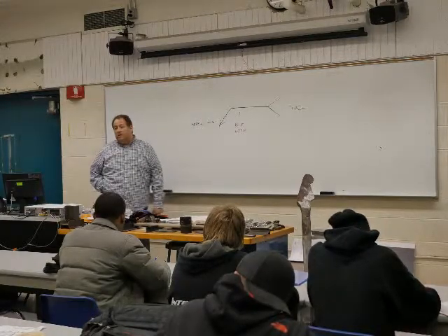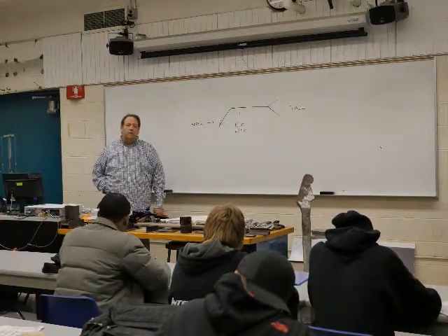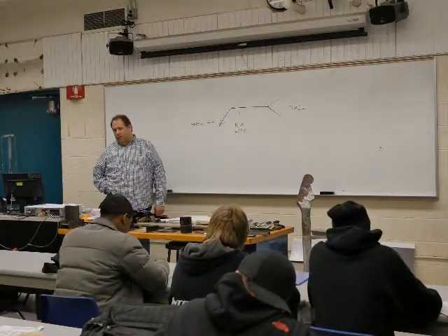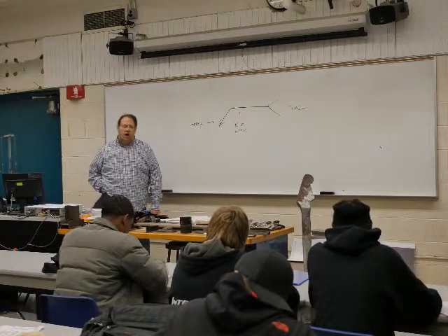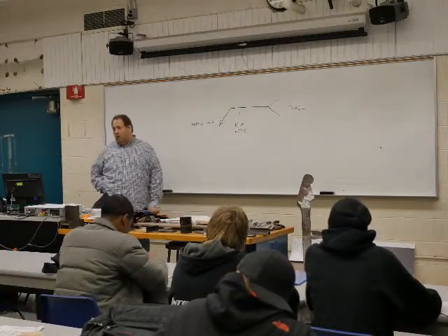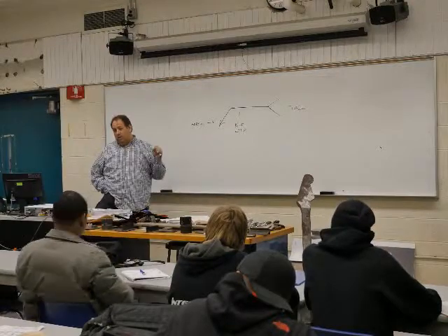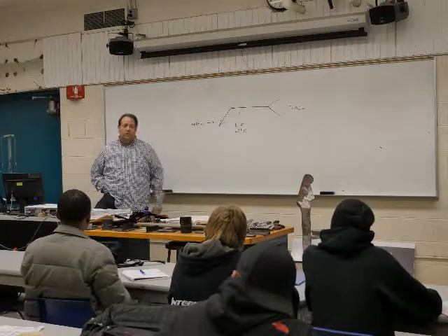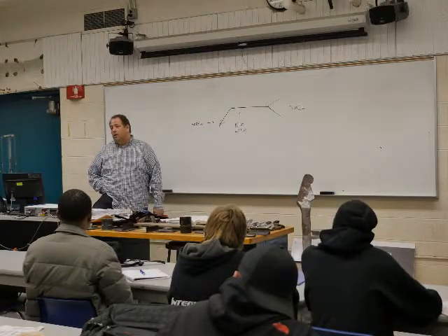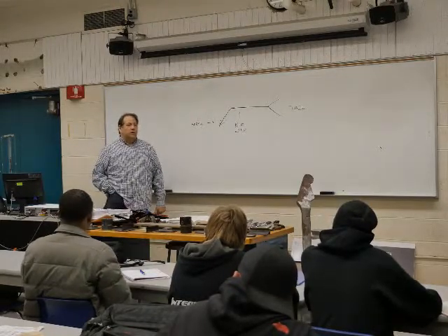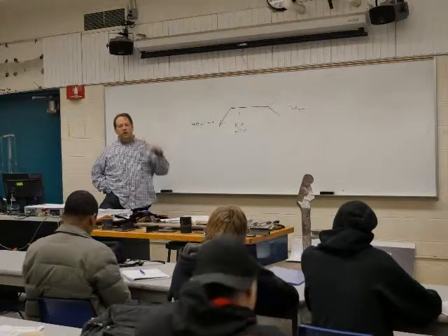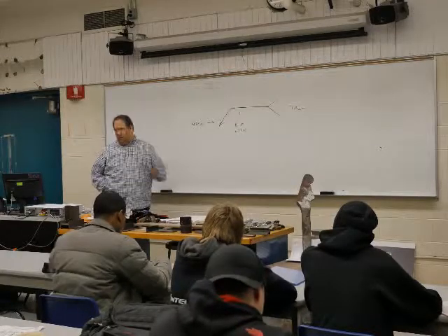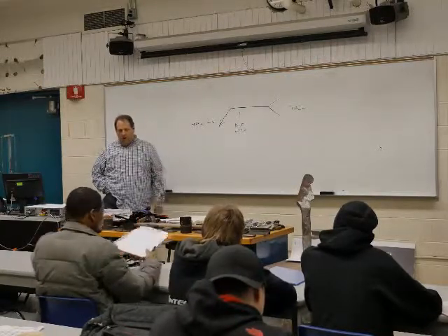So the reference line, this is where basically most of our information is stacked on or written into. I say stacked because it depends on which weld we're actually doing. Because we have, and we talked about this last week, although there's 5 of them, which 2 welds are we really focusing on? Grooves and fillets. So grooves tend to be stacked information, fillets tend to be from left to right like our normal reading pattern. And it's really depending on the way you weld it.